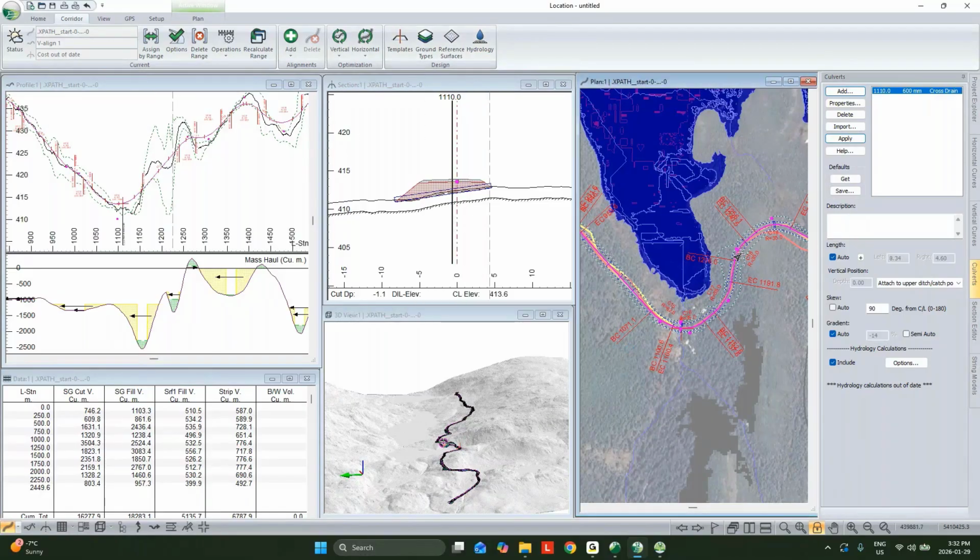So by doing that, if we calculate the streams from here, it's going to account for any water that hits our ditch and is redirected by the road. In this case, if it hits the ditch and is redirected by the road, we're concentrating more water at that crossing location, and we're robbing some from here. So we'll be able to see the impact of that using the streams tool, and where we're concentrating it at a culvert location.